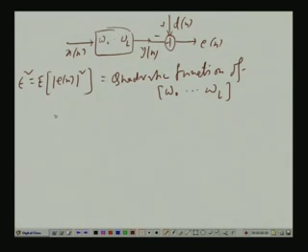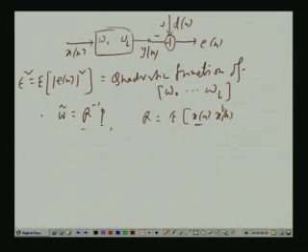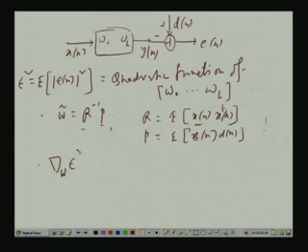We have also found out two things. One is, if we calculate the optimal filter directly, W cap is R inverse P, where R is E x n x n transpose, P is E x n d n. Other thing you have seen, the gradient. This in the morning we have seen for a particular W it was twice R W minus P vector.